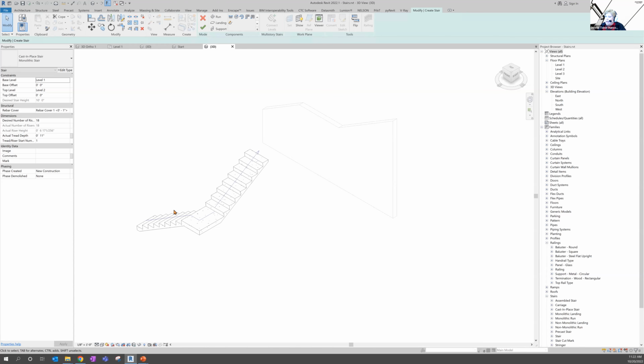So I did it by adding another stair that went from here up. And then to get the stair railing that went here and then up this extra landing, I had another stair that was invisible, 1/8 inch, placed on a work set that was not visible in any view. And I could add a railing to it that was continuous up here on a stair that didn't. Yeah, it was quite convoluted to have to do it that way.